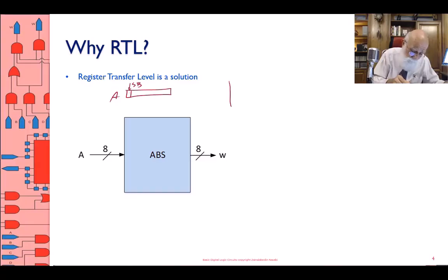So let's do this. Let's come up with a multiplexer. Put all of A on the upper input. These are 8 2-to-1 multiplexers. And then let's take the sign bit of A, which is bit number 7. If this is 0, what happens on the output is just A. If it is 1, then don't let that go through.